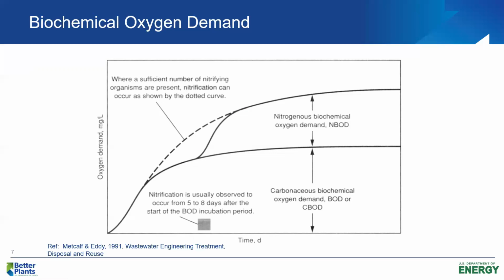So it goes anaerobic or septic. And the nitrifying bacteria are obligate aerobes, and so they're not going to do well in an anaerobic environment. So you don't have many of the nitrifying bacteria. And in raw sewage, you don't expect to have nitrite and nitrate because those are oxidized forms of nitrogen.